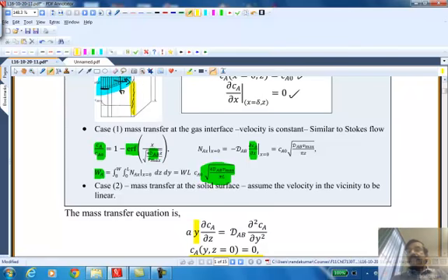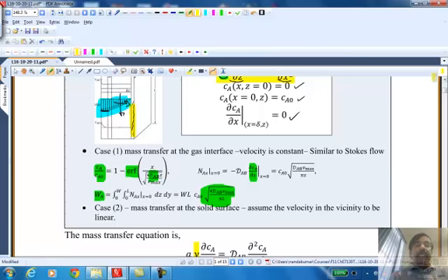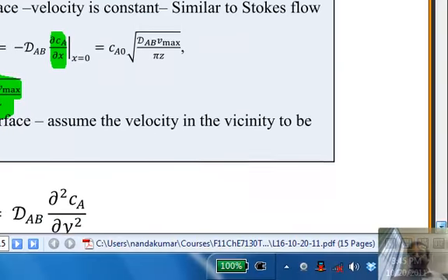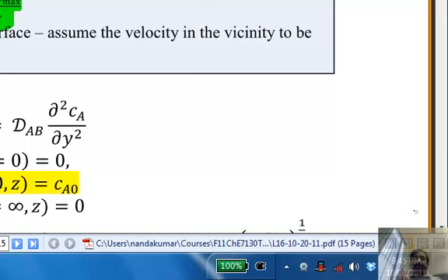And the reason that it is a bit more complicated is because we cannot assume that the flow is constant. We have to assume that the flow is linear. Once again, sparingly soluble system. Okay, so the concentration is not penetrating all the way to the free surface, but only to a small extent. Then we can linearize the quadratic profile, and once it's linear, we can still solve it in a simpler way than solving by the separation of variables. And that's where we stopped.